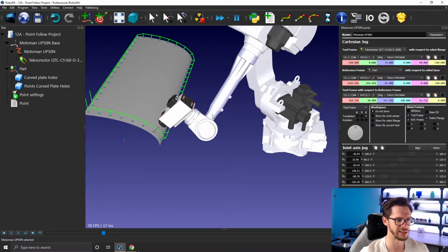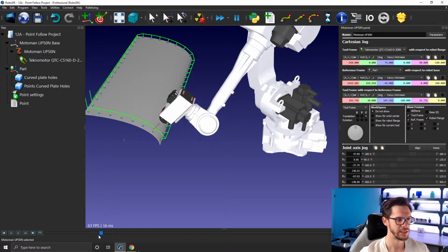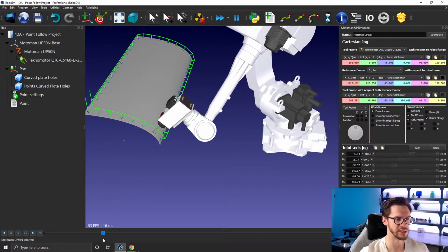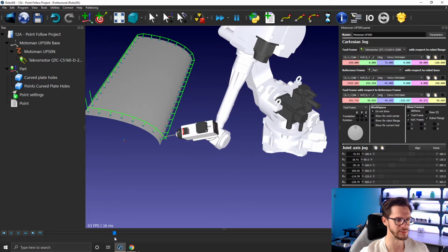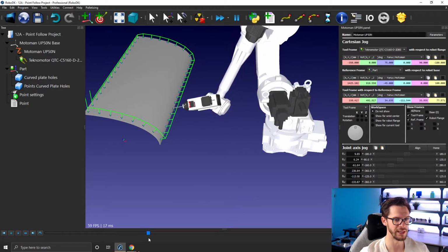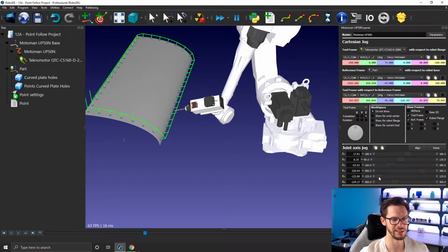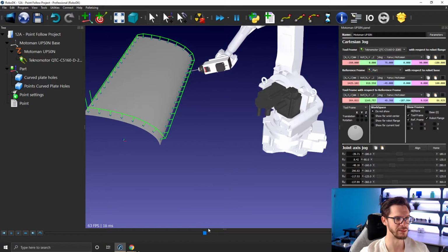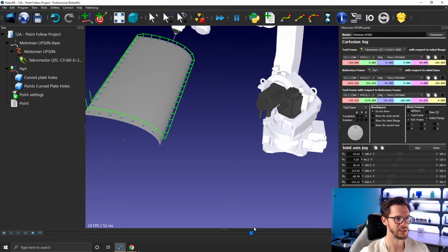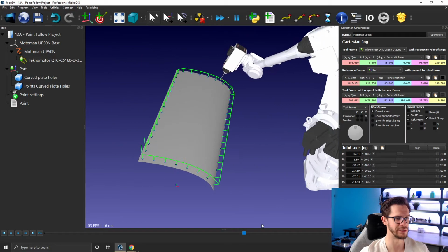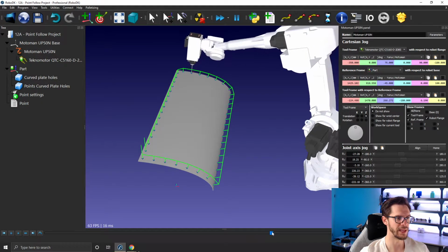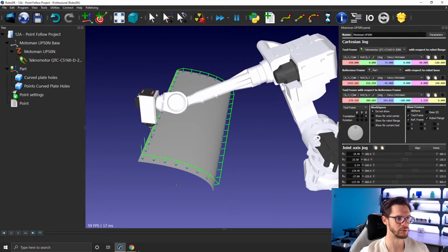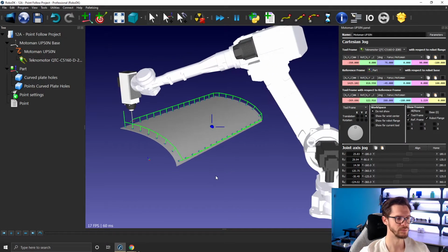In this case you can see that joint 5 is on the verge of reaching its limit, but here it will rotate around Z to avoid that. So we're fighting against joint 5 reaching its limits at all times, repositioning ourselves and moving upward like that. So that's great.